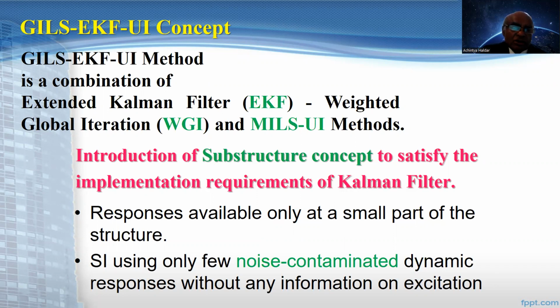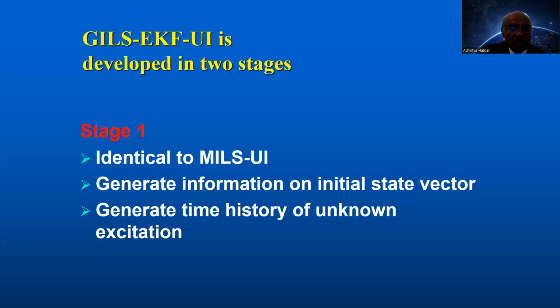Basically, the substructure concept is we take measurements only at a small part of a structure, and then we can use an iterative least squares based method to identify the excitation forces as well as the initial state vector, but keep in mind it would be noise contaminated.